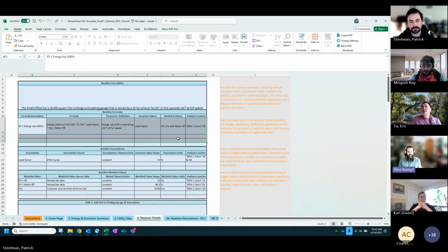Thanks. And then another question from Carl. With boilers being prescriptive, when might they qualify for custom? Carl, I think that one might be as simple as if they don't meet the requirements of the prescriptive measure. We've had a few projects where, for prescriptive, a boiler needs to solely serve HVAC systems, but there's some scenarios where you've got a boiler plant that has a heat exchanger that serves domestic hot water, a pool, and HVAC. In that scenario, that would be a custom study because it wouldn't be eligible for prescriptive.